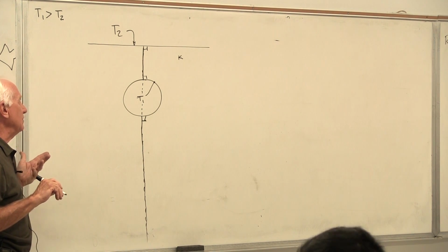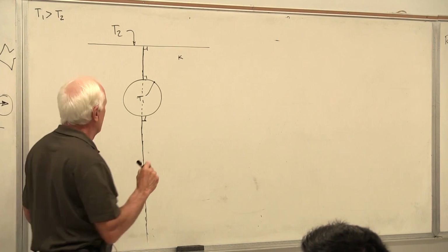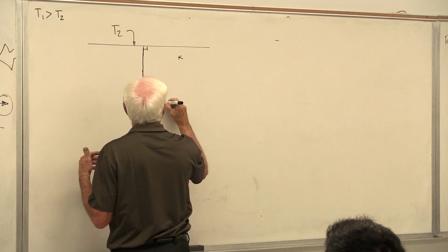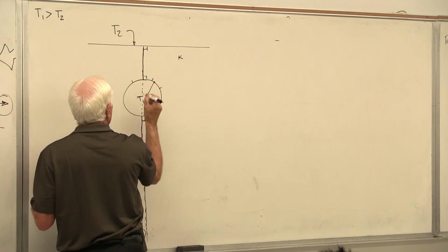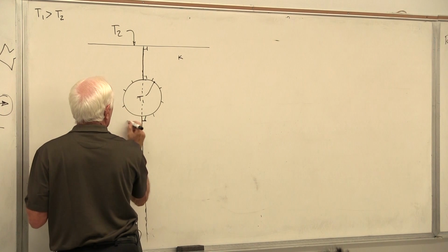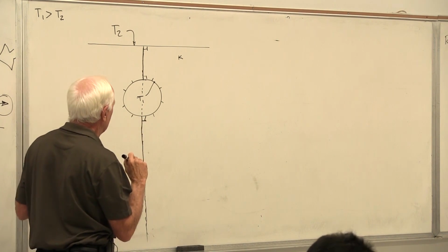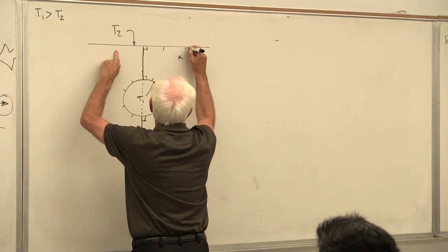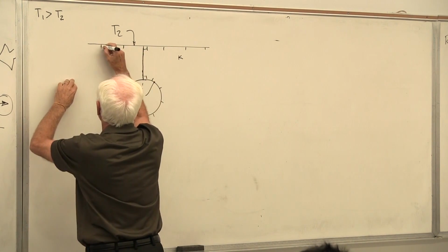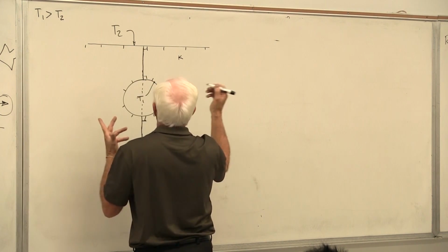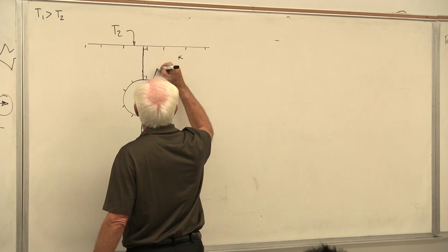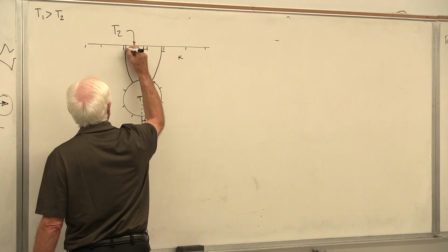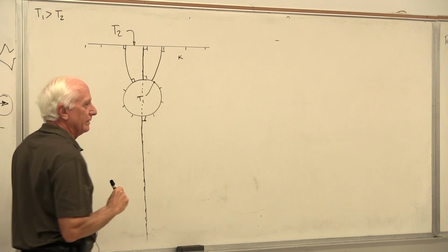But the heat that goes from T1 to T2, I know, rule 3 or 4, it leaves an isothermal surface at right angles. That's the rule. It leaves an isothermal boundary at right angles. And when it gets to the other isothermal boundary, it enters that boundary at right angles. Okay, take the easy one. I think heat leaves here and goes out here. Of course. Leaves here and goes out here. Yeah, sure, there. Okay, keep going.